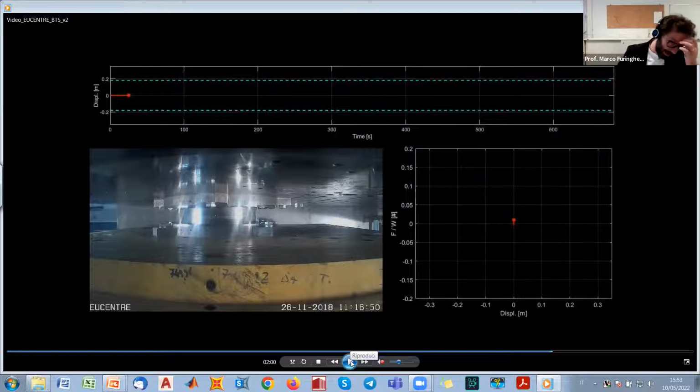But what we have observed in this research is that even though the maximum displacement is overcome, the overall force response is pretty stable, and it can be modeled just as an increase of the friction coefficient. So the damage which occurred at the sliding material can be just modeled as a little increase of the friction coefficient.